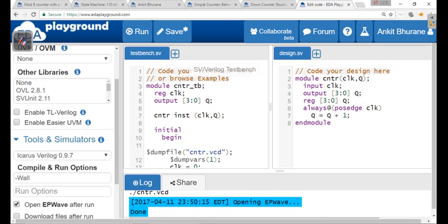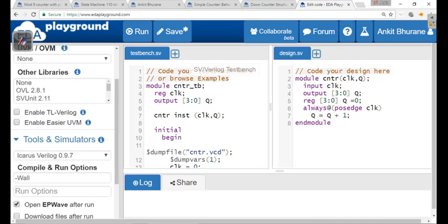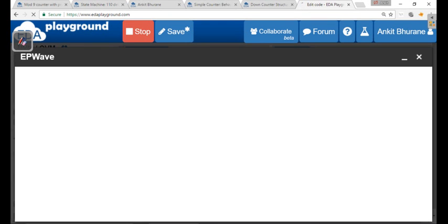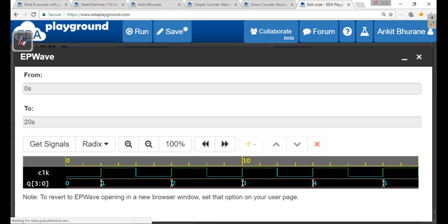You can very well specify that here, right? Anyway, it is defined as reg. So what I can do is simply specify the initial value as, let's say, 0. Then it would increment. If I run this, yeah, I should get this incremented. Okay, I'm getting this incremented output 0, 1, 2, 3, 4, 5. Try implementing a down counter using negative edge triggered and so on. Go for it. This is very simple, isn't it? You just need to specify one line here.